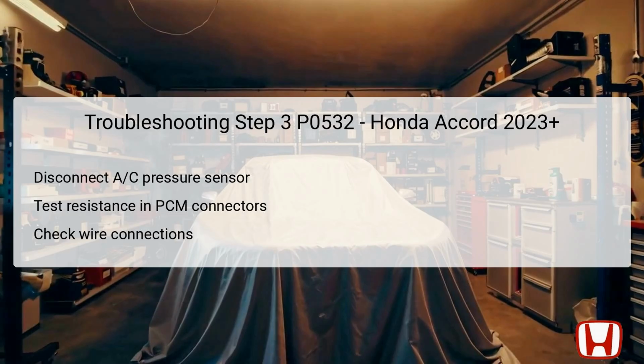The voltage reading across the AC pressure sensor needs to indicate that resistance is suitable, generally suggesting that there should be less than 1 ohm of resistance along the involved pathways. Additionally, thoroughly check for any visible damage or corrosion at the wire connections. This inspection can uncover hidden issues that might not be apparent, and it's crucial for ensuring each component in the circuit is working correctly and efficiently.